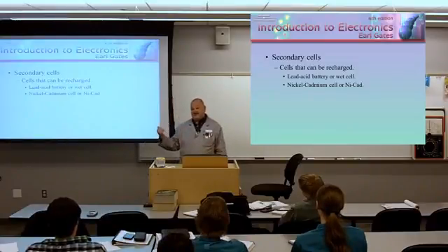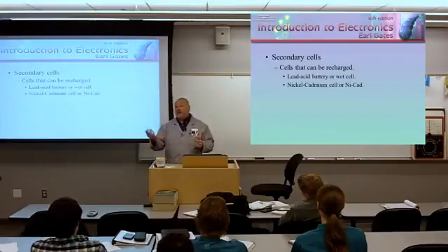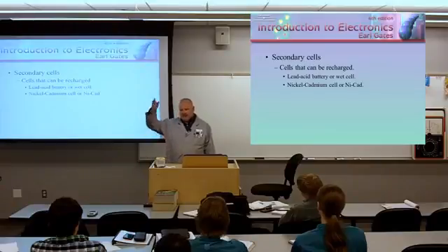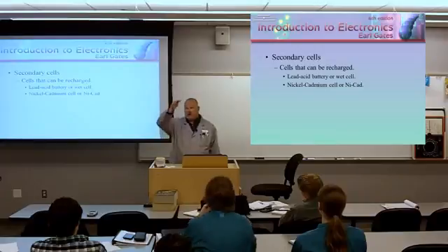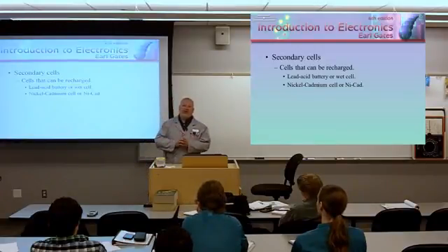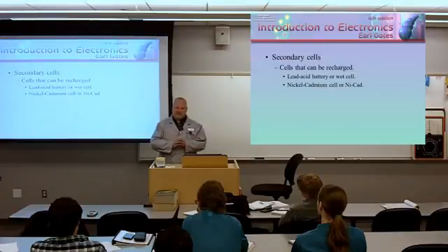It's because I understood how to take care of NiCads. What I did is I made myself a dummy load, and when the battery got low, obviously if it was a birthday party or something that I wanted to video, I could recharge the battery. But at least on a regular basis, I would discharge it all the way and then charge it all the way. And by the way, with nickel cadmium cells, when I say charge it all the way, that doesn't mean slap it in your quick charger.